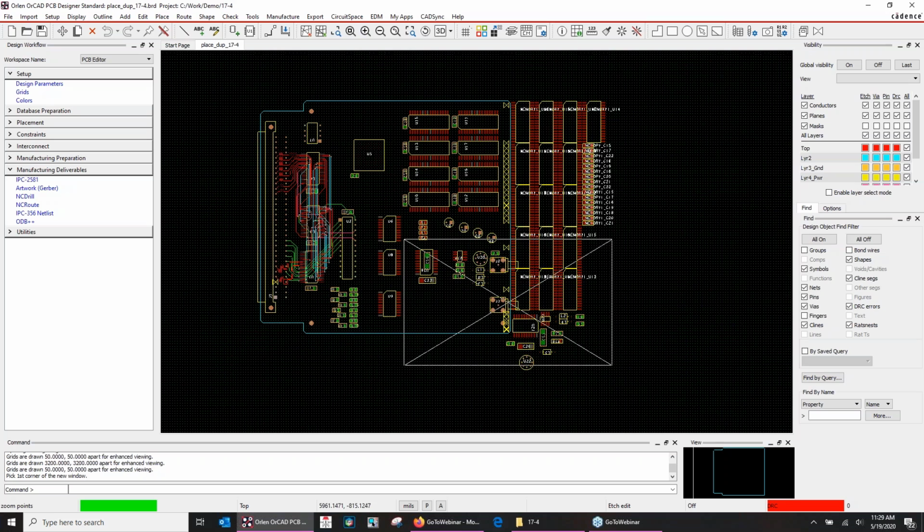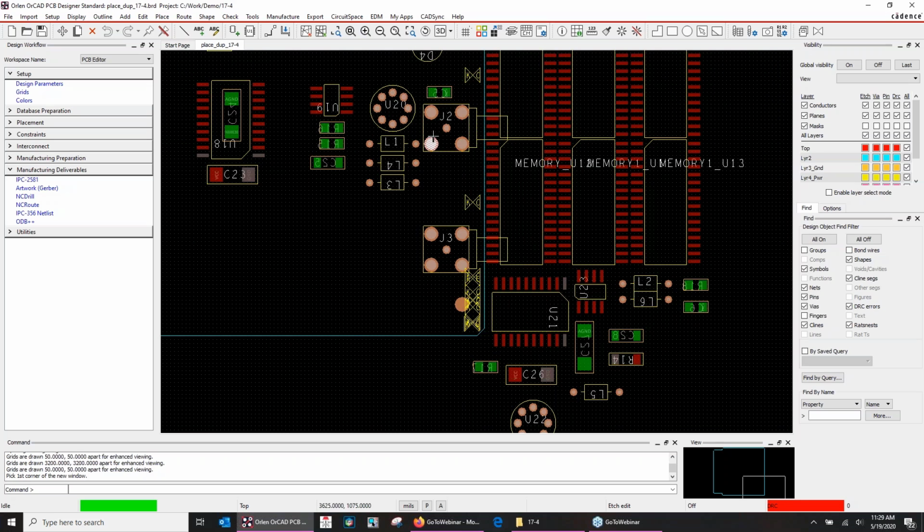I want to come down here, and we've got a circuit laid out where here's my RF connector. I've got this little circuit in here, and I want to duplicate that. This one down here that's scattered apart, I want it to be exactly the same. In Pro, it would be a two-step issue. I would just define it, grab all the parts and define it, give it the origin, and it's done.